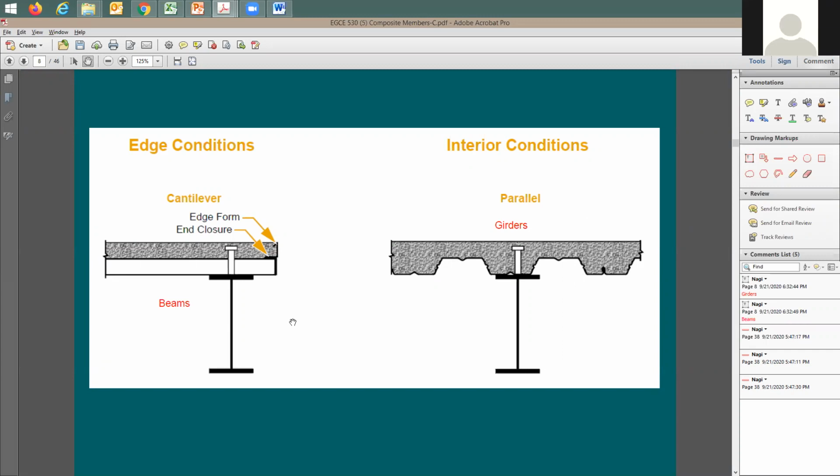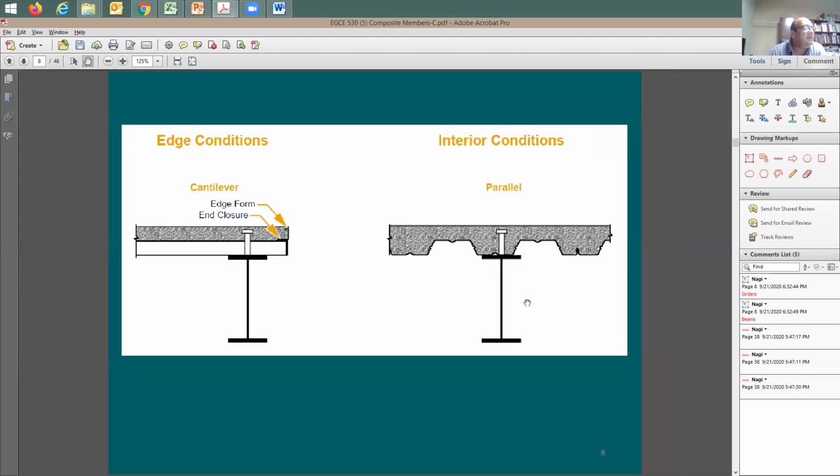Professor, for girders, what's the thickness of concrete that we consider? Are you talking about the project? No, just in general. In general, you'd like to start with 3¼ inch lightweight concrete if possible. Are we considering above the steel deck, or right at the top of the beam? The 3¼ is going to be whatever is above this point. So when I say 3¼ above W2, or W3 with 3¼, this is the way that we say it.